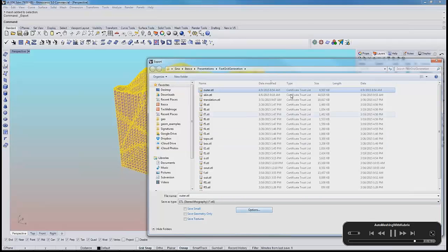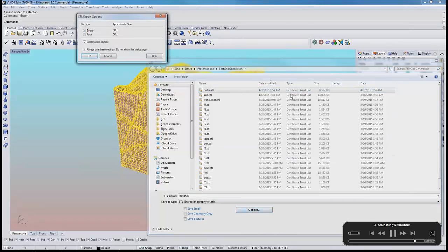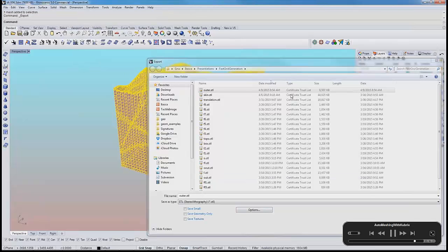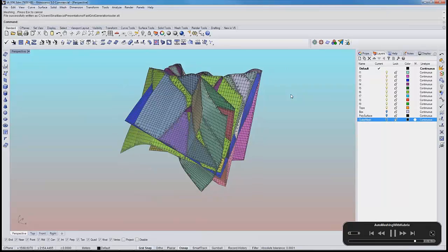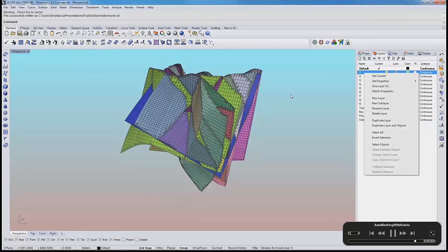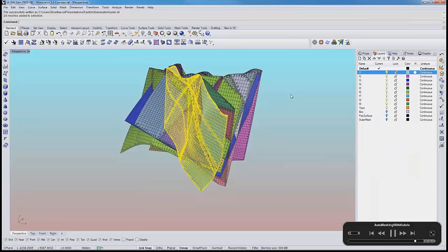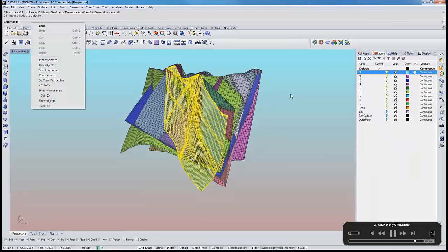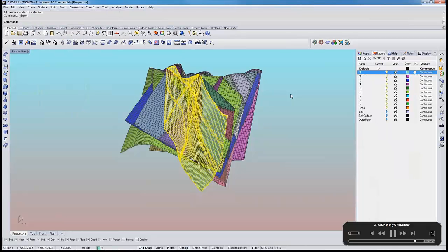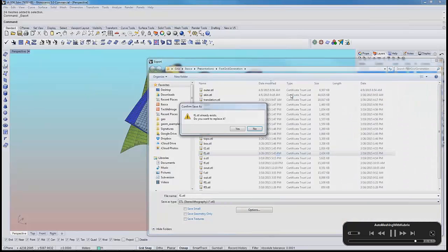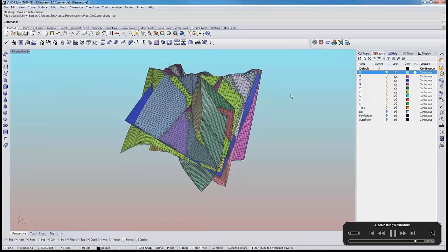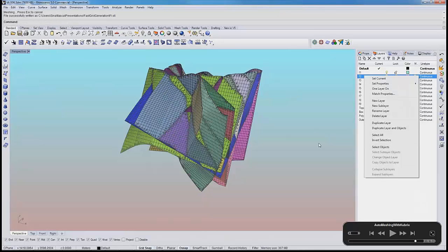Now I export all these surfaces as STL files. So I will end up exporting essentially 10 STL files, one for the outer.stl and for each layer, I select that layer and I say select objects, and all the meshes that are in that layer are exported as f1.stl, and all the meshes that are in the F2 layer are going to be exported as f2.stl.